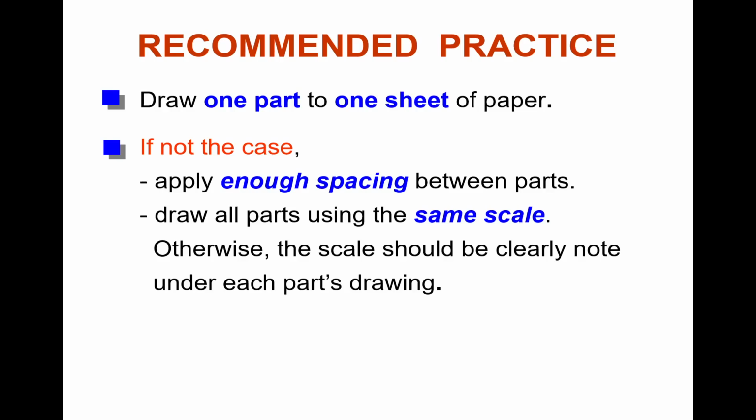Okay, you can't draw it if there is one part, for example, the first part you draw using scale 1:1, and the second part you draw to scale 1:2. Tak boleh, it's not consistent. So one sheet of paper, you should draw that one part on one sheet of paper using the same scale.